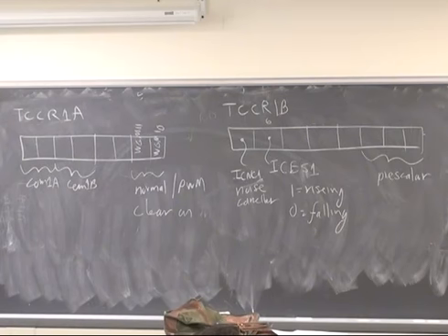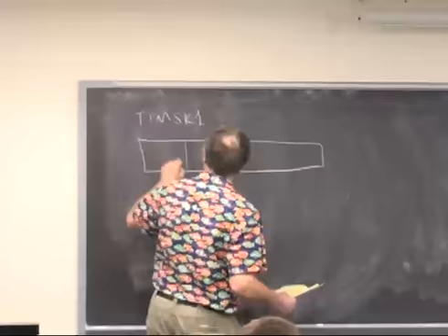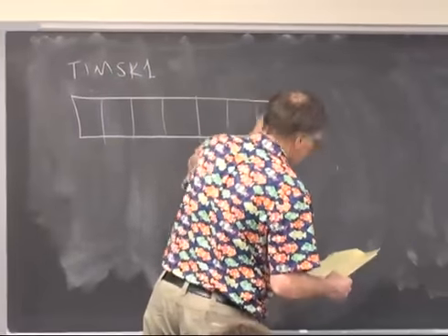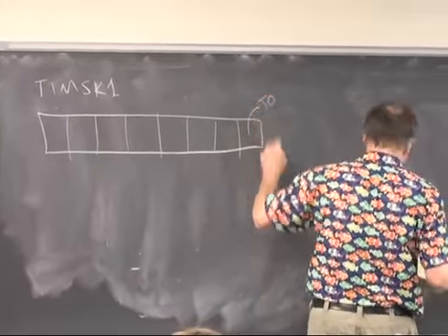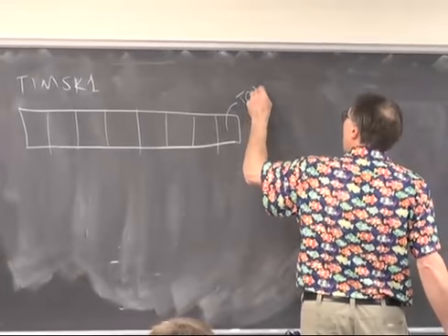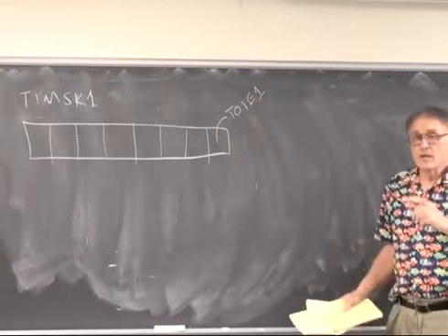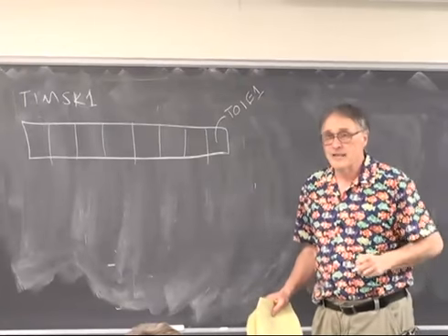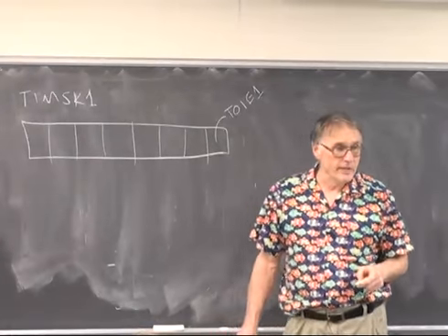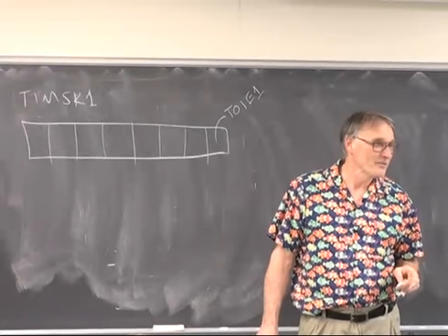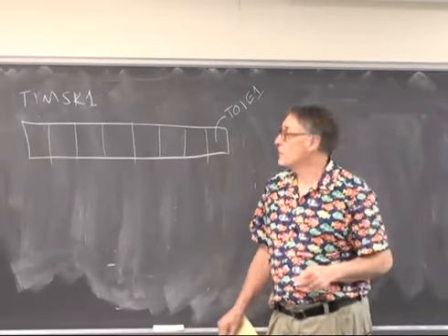The timer mask 1 register now has a couple of extra sources for interrupt service routines. You have TOIE1. That would be the timer overflow interrupt. That could be very useful in this lab because if you get an overflow, it means that you've certainly run the timer for too long and you are therefore not going to get an accurate period.